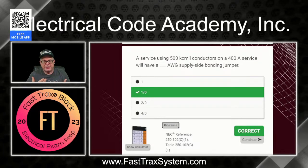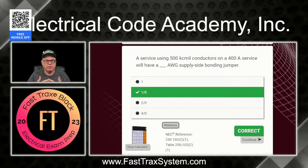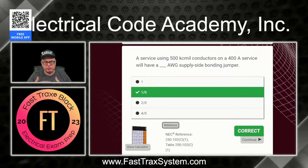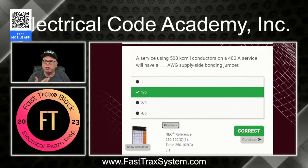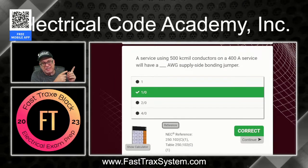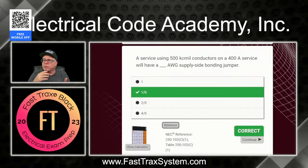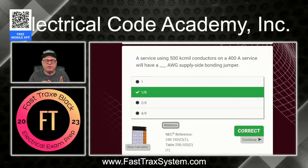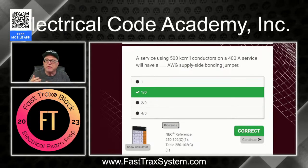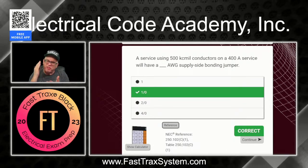You should be able to look at that, and over time, you're going to know that 28's main bonding jumpers, okay? You're going to be looking at 66, and that's going to be grounding electrode conductors. You're going to know that when you see 102, that's going to be the minimum sizing for the grounded conductor, although it still has to handle the calculated load for the grounded conductor, but it can't be less than this table. You're going to do supply side bonding jumpers, system bonding jumpers, main bonding jumpers. All of them are going to send you here to this table. So you just want to get familiar with it. And that way it's going to save you a lot of time on the exam.